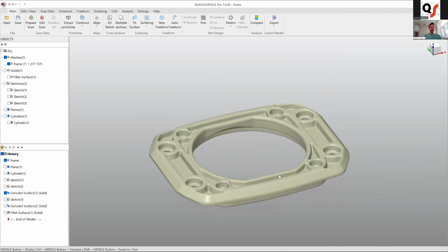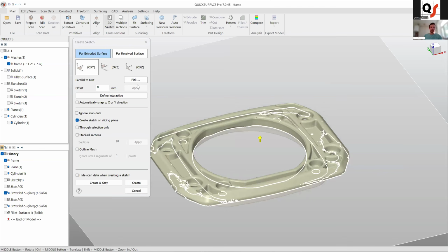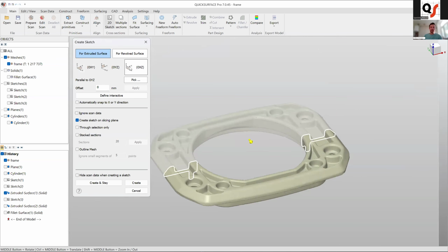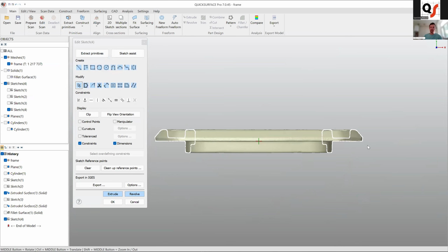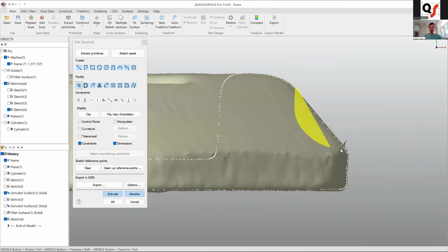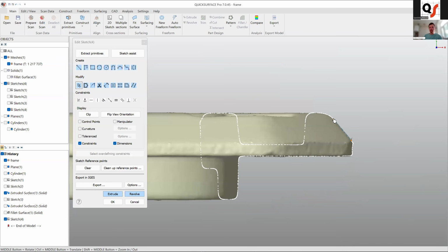Well, talking about this topic, actually, we have an option to take a look at what it should be. You can create just a simple 2D sketch, fit a line to this chamfer surface, and fit just another horizontal line, and you can understand. So it's like 50 degrees.